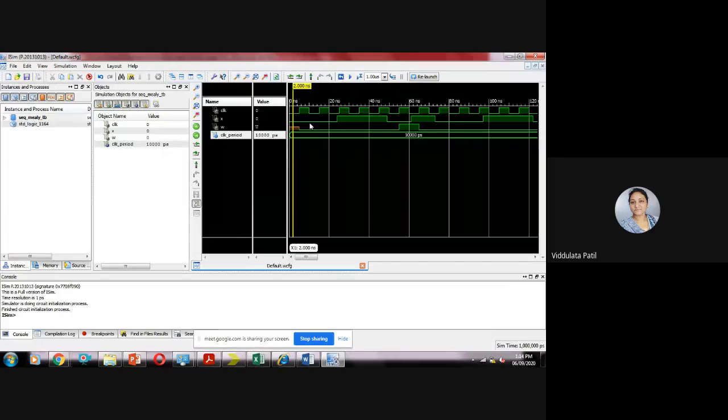Just see here. If you look at the voltage level, if you check the level, it is lower than the level of 1 here. Okay, but it is not equal to 0 also at this condition. That means for 5 nanoseconds your output is at an undetermined or unknown value because you have not set a value for this W initially.